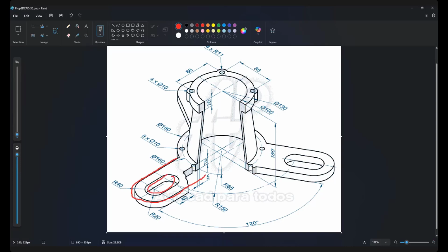But if you can see, it's a repeated thing. Repeated. 1, 2, 3 at the back there. We have 3. So in Solidworks, you don't have to do it 3 times. Once we draw one arm only with a slot, then we can do a circular pattern in Solidworks, so it will duplicate it. Circular pattern, number is 3, so you make 3 of it. You only do it once. About this slot, I will show you.